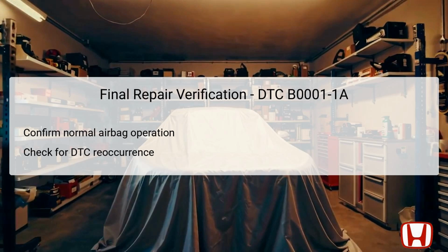Testing should include ensuring that the airbag deploys correctly by conducting functionality tests while following manufacturer guidelines. Additionally, inspecting for any lingering symptoms is critical to provide assurance that the previously noted problems have been resolved. This confirmation step is paramount to ensure the safety of the driver and passengers in the vehicle.